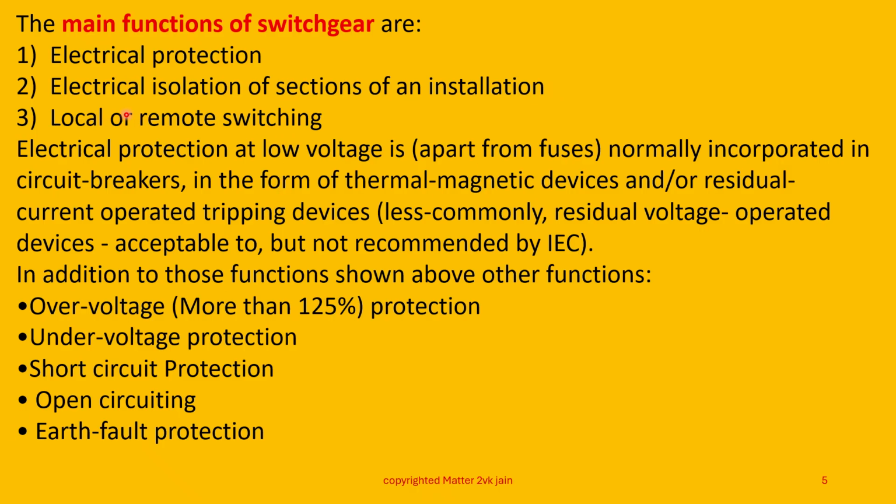Third, local or remote switching. Electrical protection at low voltage is, apart from fuses normally incorporated in circuit breaker, in the form of thermal magnetic devices and or residual current operated tripping devices. Less commonly, residual voltage operated devices, acceptable to but not recommended by IEC.